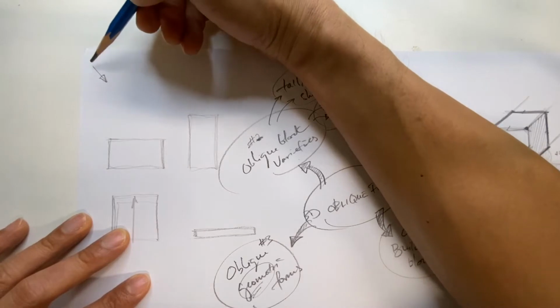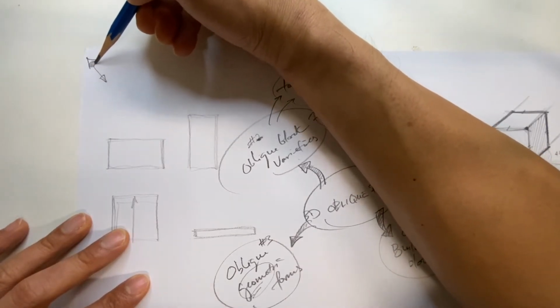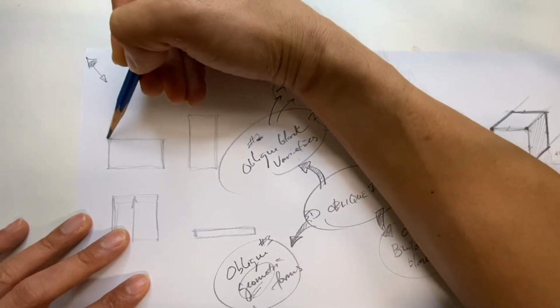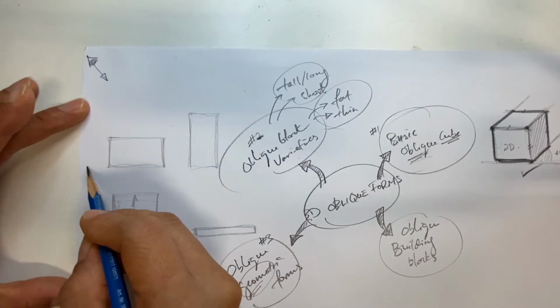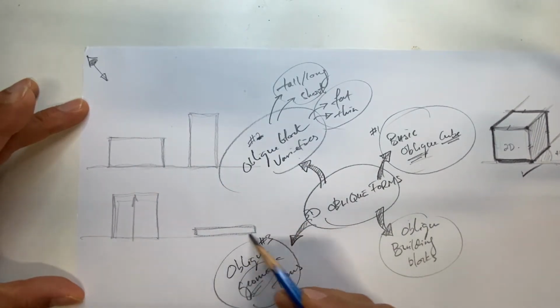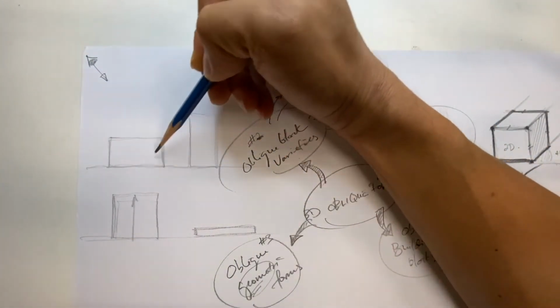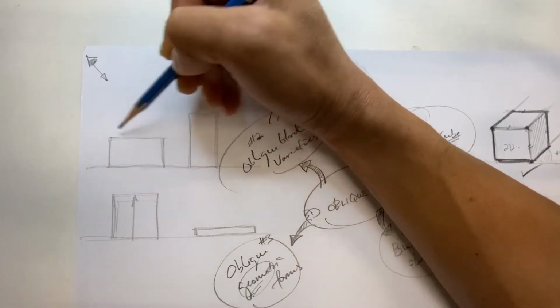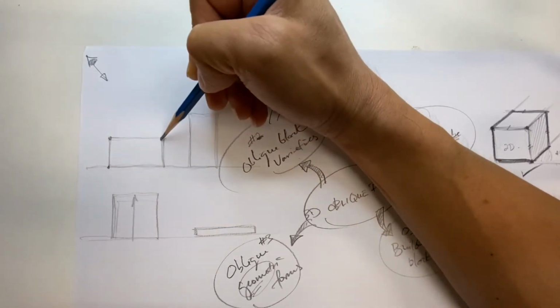So if I want to pick a view from the left, I put my eye here. The lines to be projected at 45 degrees will be to the left at 45 degrees. So if this is the horizontal, the ground, then because these are blocks, there will be 3 points which I need to project to the left. So this is the 1, 2, and 3.